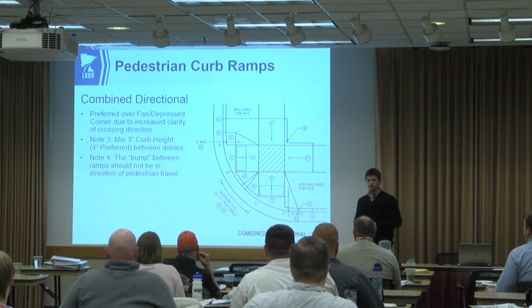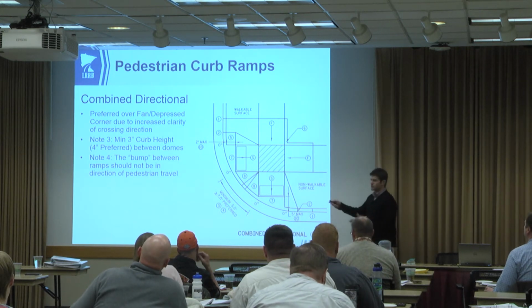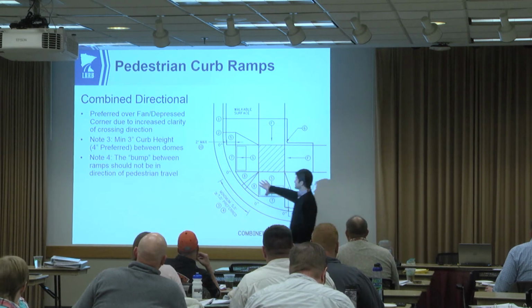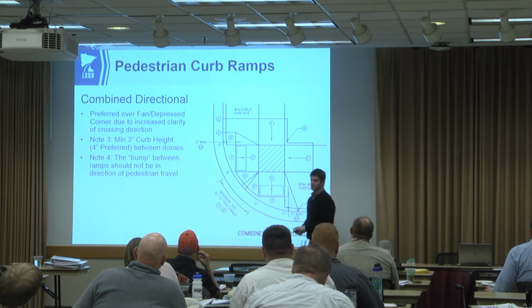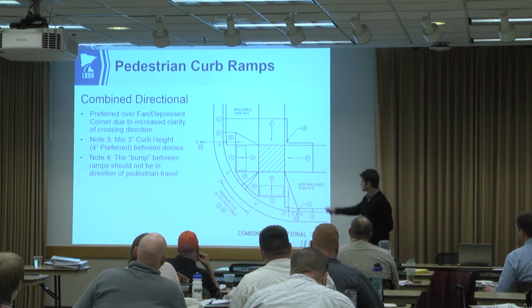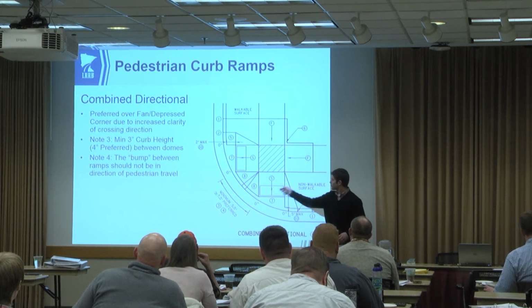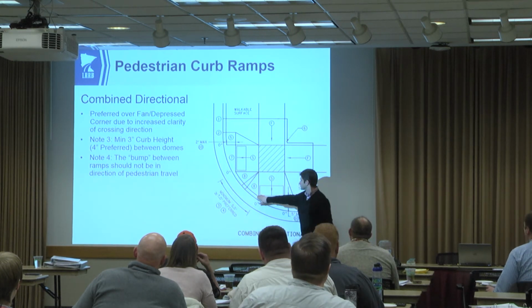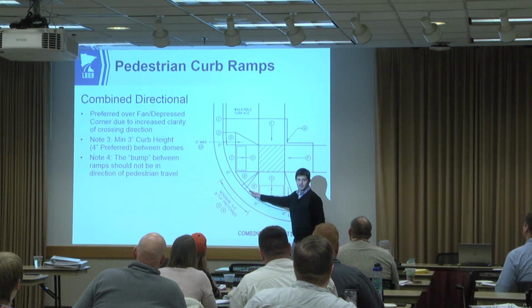The reason you wouldn't use it is if the geometry, as she said, the geometry or the curb radius doesn't allow you to get enough space between these ramps. So what a designer is going to do is, you've got a sidewalk coming this way. You'd extend the edge of the walks through the curb line. Do the same thing with the other walk. Where the inside edge of the walks intersect the curb here and here, you're going to need to transition the curb at that 10% maximum rate, right, to get back up closer to full height.